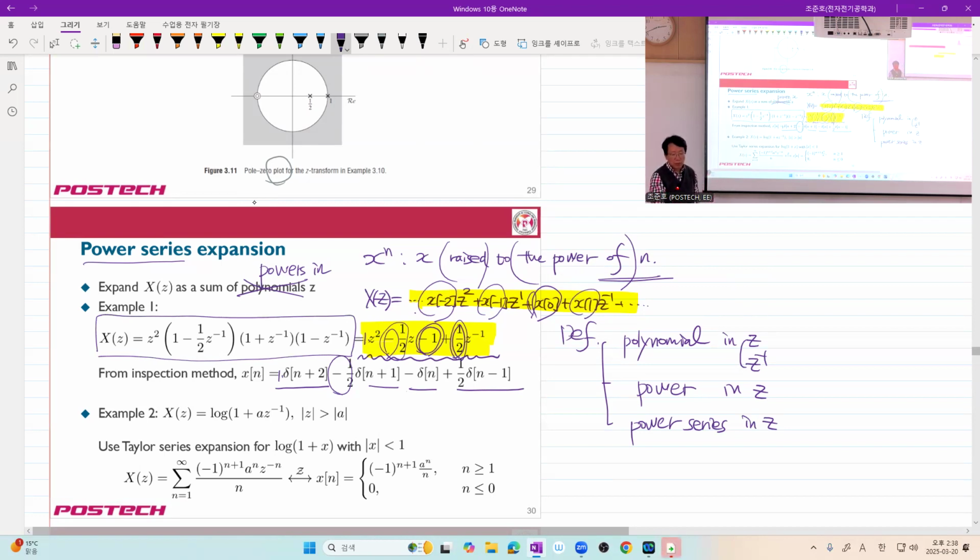It does not specify, but since you have this expression already, the region of convergence must be the entire complex plane except the origin. And this expression also matches with your observation, right? Z cannot be 0. For all other complex numbers, it's okay. That's why you just compare the coefficients, right?